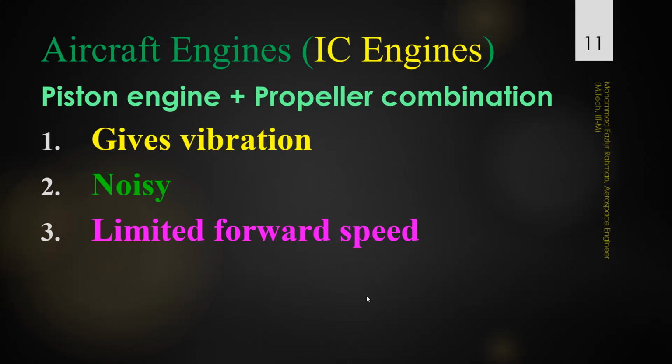So there are chances that the propeller reaches the sonic barrier before the vehicle does. The vehicle may be moving at a subsonic speed, but the propeller may start operating at supersonic velocity, and the moment it does, it starts encountering shocks, and the shock generates a lot of new problems.